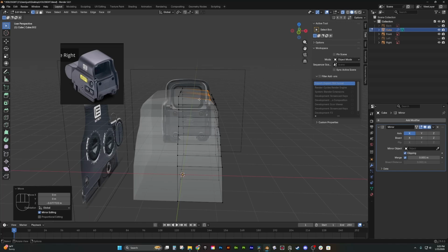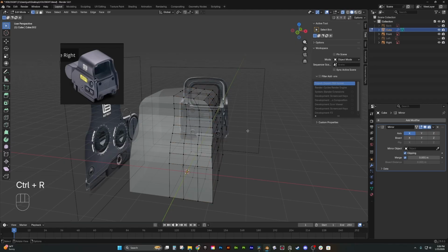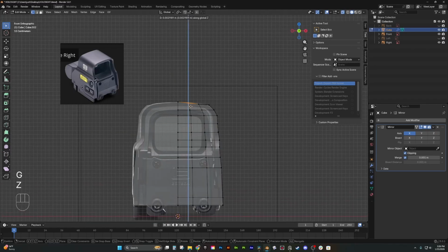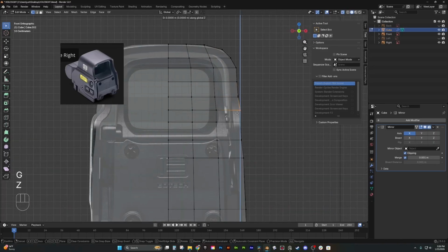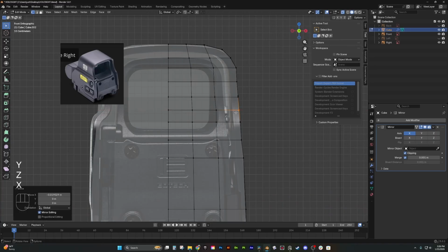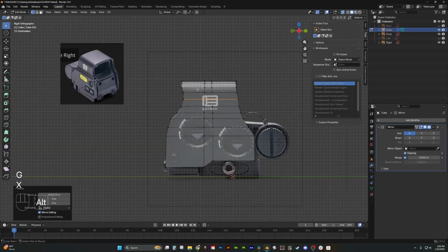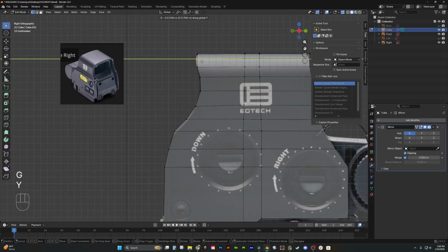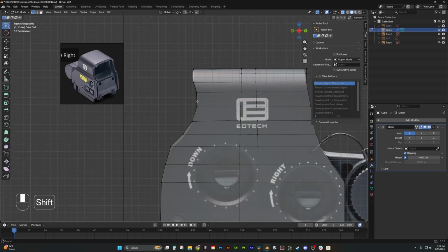And now it's a good opportunity for us to add edge loops in this direction. So I'll add two, let's add two for now. I'll add 2 edge loops, go to the front view, and we can lift these ones up on the Z axis. And let's make sure we have these a little bit straighter and more relaxed. So all we're doing is selecting vertices, edges, dragging them in and out. And as you'll notice, this sort of peaks outwards a little bit more.